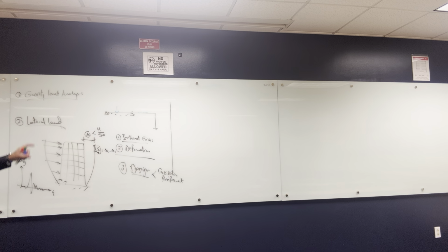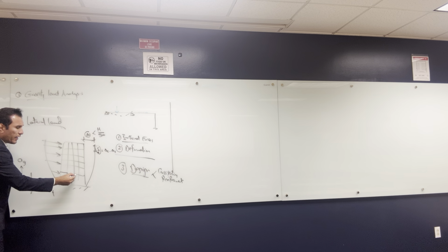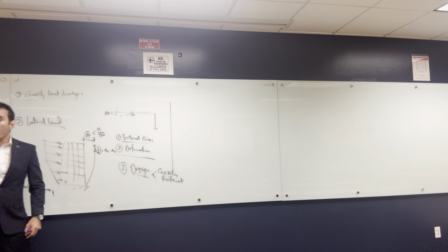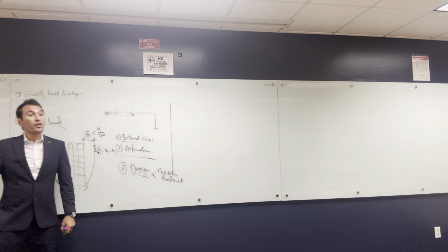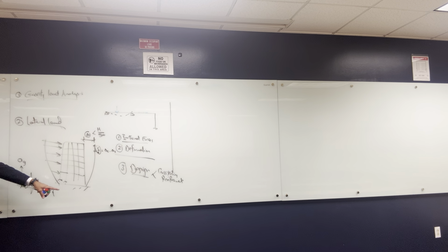All right, so we have all of these. To do this, I need to teach you something. To do lateral analysis for a multi-story building is a really huge mathematical problem, because you have multiple degrees of freedom. Every single point here can move separately in X, Y, and Z and rotate about X, Y, and Z. So structural engineers started looking at ways to simplify this building to a simple model so that we can solve a simple dynamic problem. But to simplify this, we need a way to lump the building into a simplified model. But before I do this, let me do something with you.